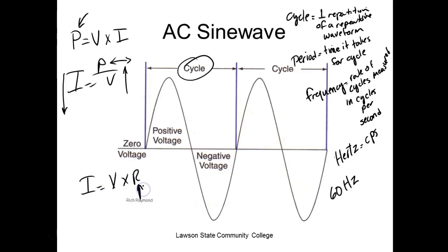What determines the amount of resistance a wire has? The size of the wire, the material of the wire, right? You understand, and the temperature of the wire, and the length of the wire. So there, Alabama Power is trying to give you that power through a wire. A wire has resistance. If it's got resistance and I put current through it, it's going to drop a voltage. So the lower I can make that current, the less voltage my conductors will drop.